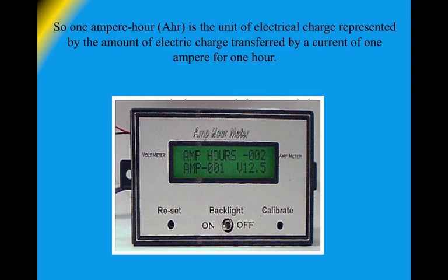It is a good method, it is a good standard tool to keep in the toolbox, but for day-to-day measurements of capacity of a working battery, we use amp hour meters, and we try to make sure that they're advanced enough to give us the readings we need and to adjust for aging batteries by adjusting the Peukert's constant.